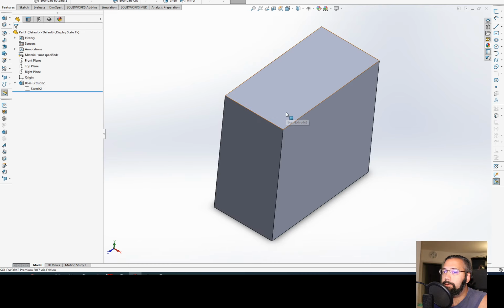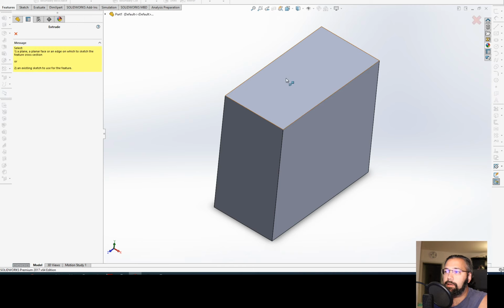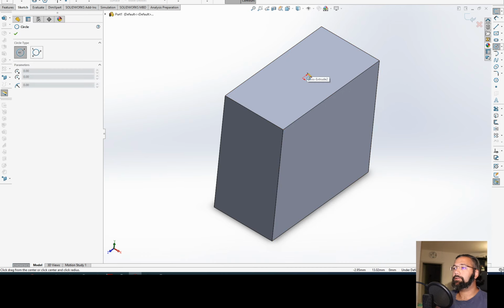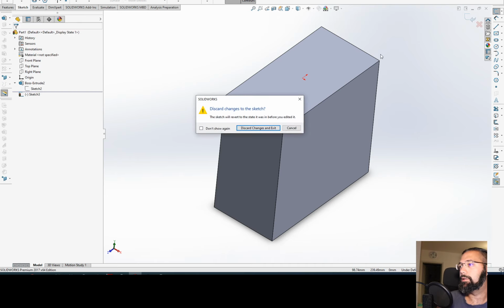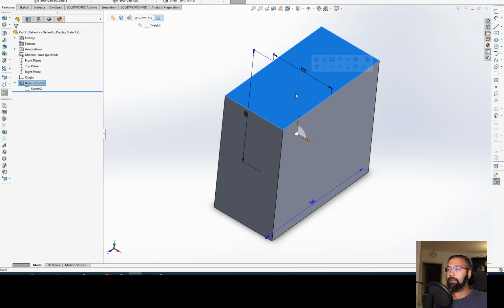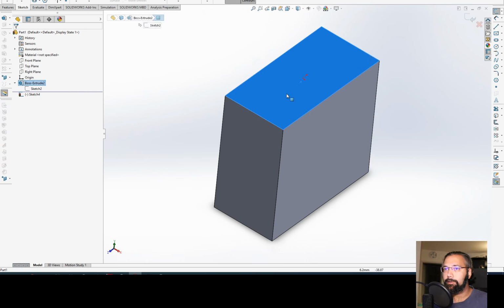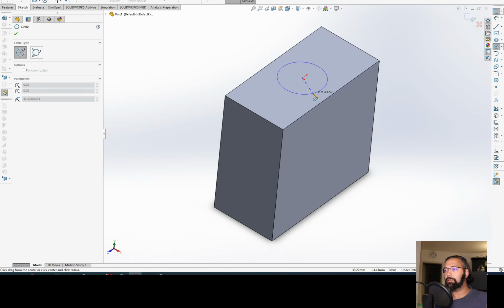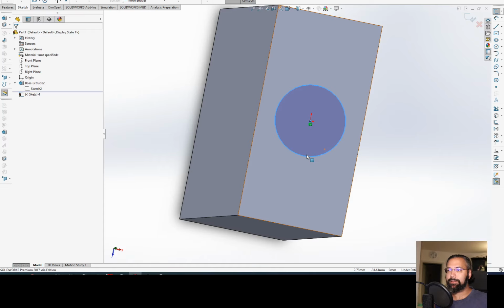And yeah, so you have your volume. You can now do things like remove material. Let's take a circle. Let's go back one thing. I pick this face, I choose sketch, I go to a circle, I place the center,